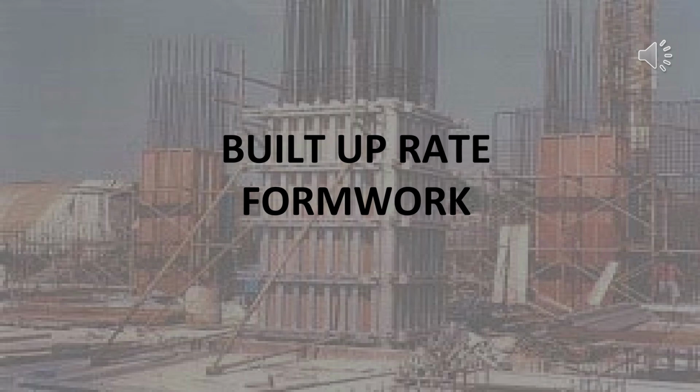This slide introduces the next topic, built-up rate for formwork. Here, we will learn how to calculate the cost of formwork by breaking it down into labor, materials, equipment, and other related components. The goal is to understand how each element contributes to the final formwork rate used in estimating and pricing.